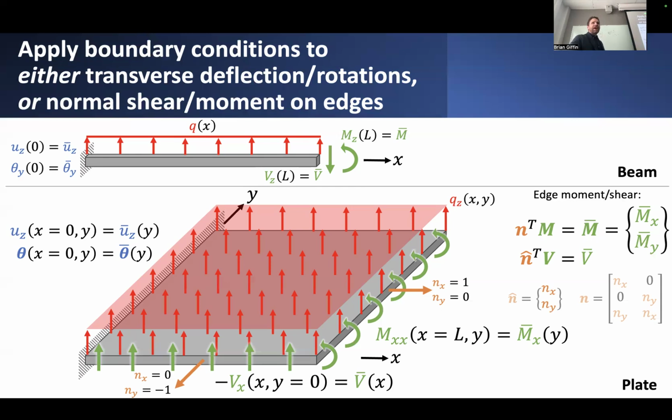However, again, as I said, coming up with analytical solutions to these plate bending problems in general requires solving that biharmonic equation, which doesn't always admit analytical solutions, at least not easily and not for general boundary conditions and loading conditions. But it can be done for certain types of problems, and the solutions you get look kind of like the ones that we did for these two-dimensional elasticity problems. You can visualize them in this two-dimensional sense, maybe as a contour plot to visualize what the deflected shape looks like.